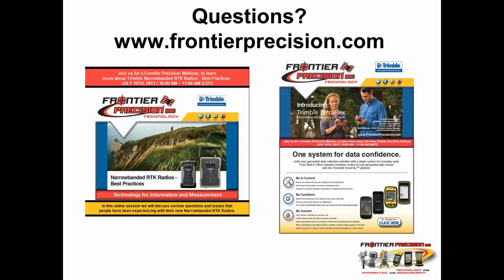That's what I would probably do. I'd create a project with the UTM, bring the photo in so it comes in the right place, and then change the coordinate system to your county after the photo's been imported, and that should do it. I'd have to test it to make sure, but that's how I would do it anyways.